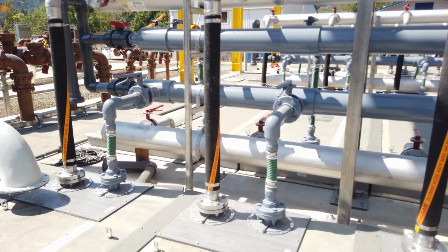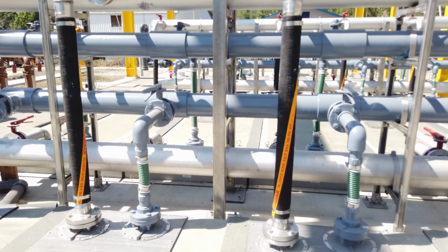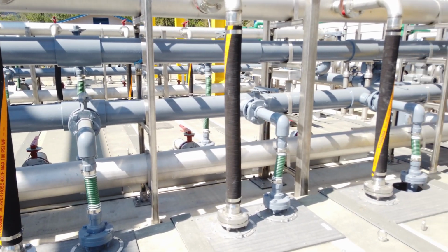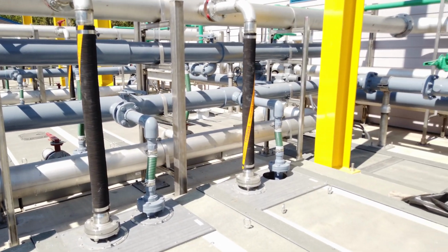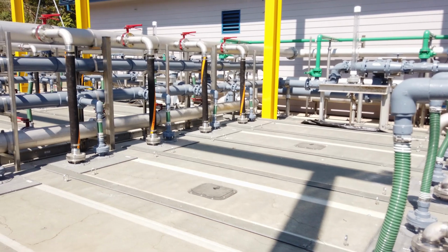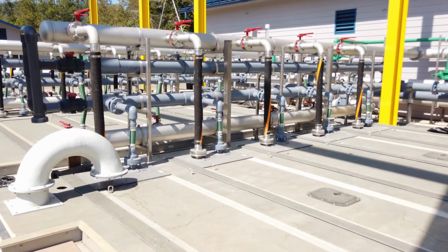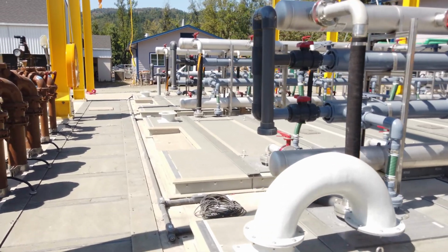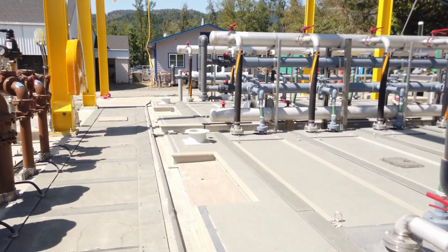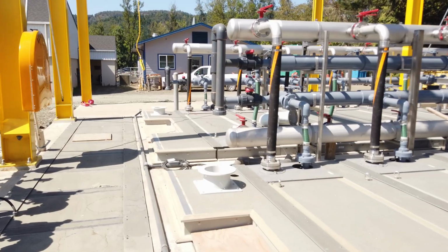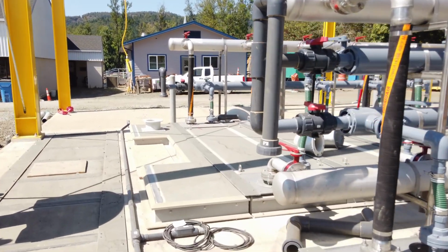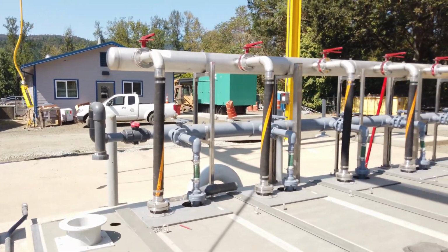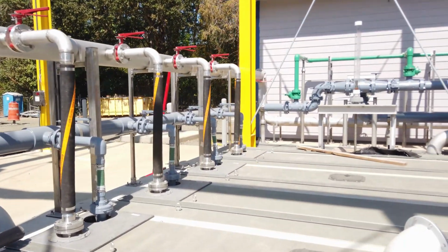Each MBR tank has permeate suction headers for the upper membrane cassettes and permeate suction headers for the lower membrane cassettes. Permeate is pulled from the membranes with permeate pumps in the control building. The permeate pumps filter the mixed liquor in production mode. The pumps operate for about 9 minutes and then relax for about 1 minute. This 1 minute relax period allows the membrane to relax and air to better clean the membrane surface.